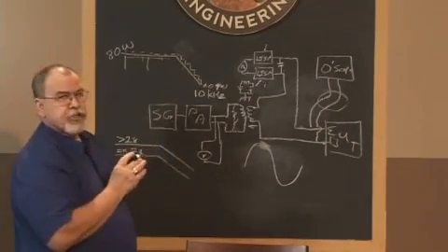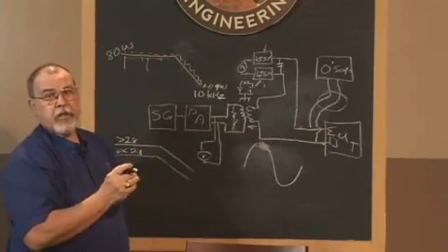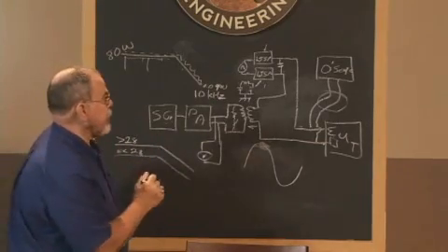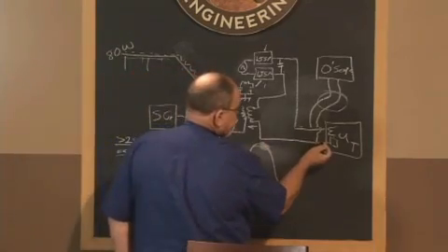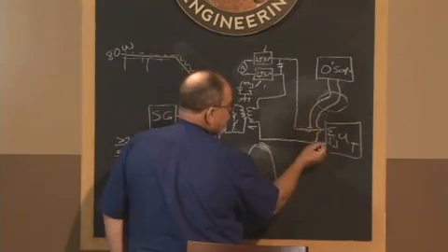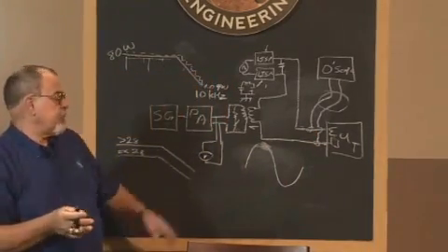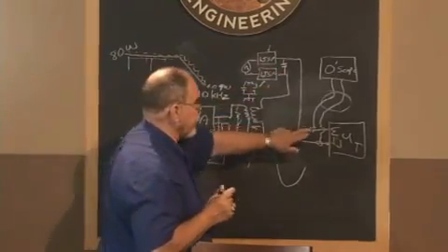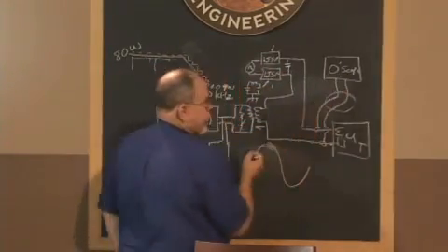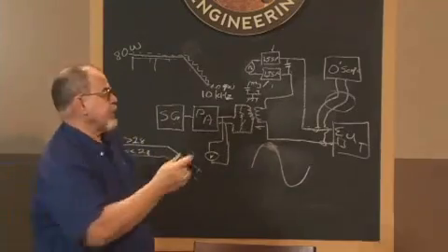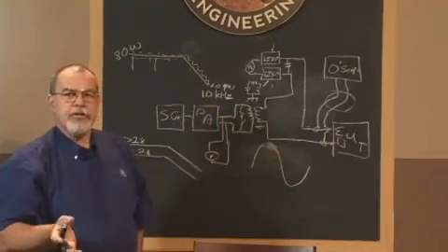Okay, we've got this safety problem going on too. And I didn't mention it so far, but now we've got 60 hertz appearing here and here. Now if I've got a grounded neutral, my neutral lead of my power here connects to my oscilloscope body. If that's grounded and the scope is grounded, no issue.